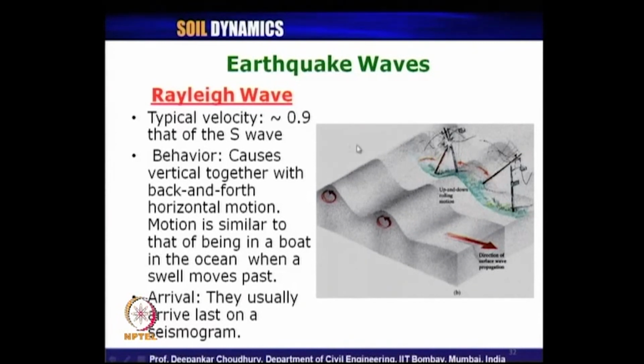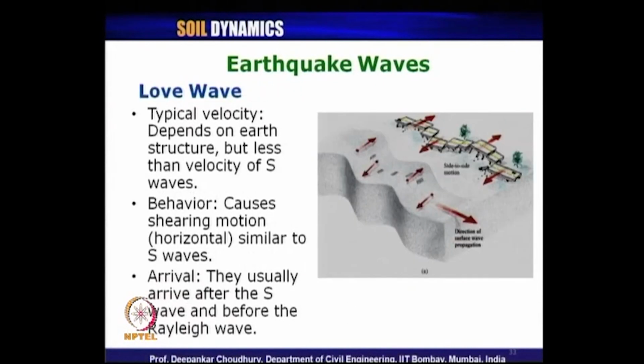So, that is why it is said Rayleigh wave is the most damaging one for the structures constructed on the ground, not only because of its behavior of motion of the particle due to the wave propagation, but also, as I have mentioned, about 2/3 of the energy generated in the earthquake is finally released in the form of Rayleigh wave.